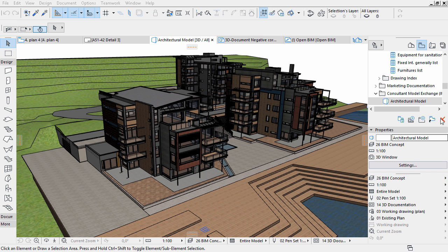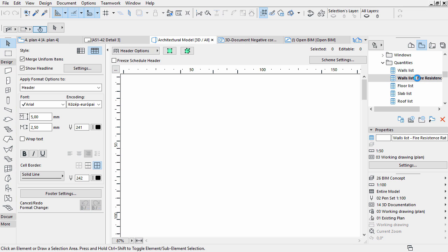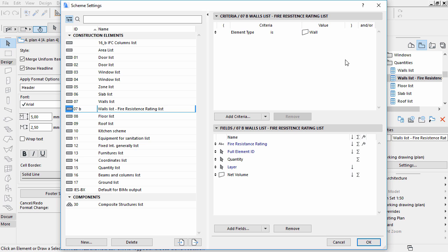At any phase of the project, we can use interactive schedules to create schemes and lists of existing and imported elements. These schedules can be saved in spreadsheet format. For example, list the project's walls by quantity and fire rating. This schedule summarizes the major properties and quantities of walls having a particular fire rating schedule. It's refreshed automatically if any element is modified.